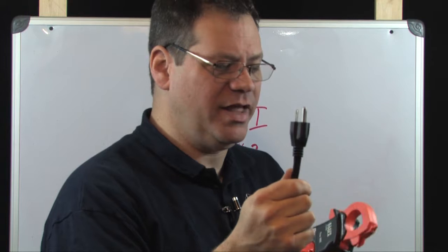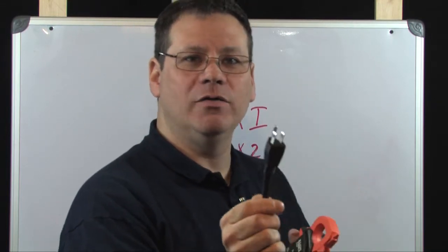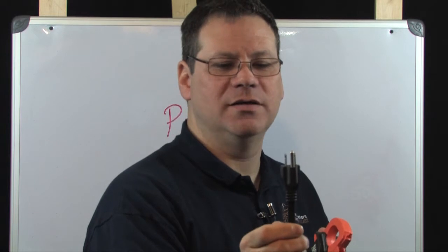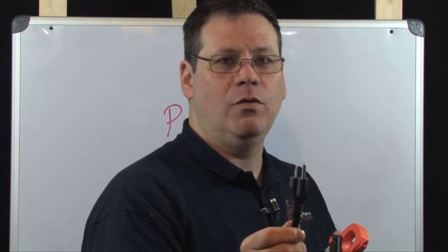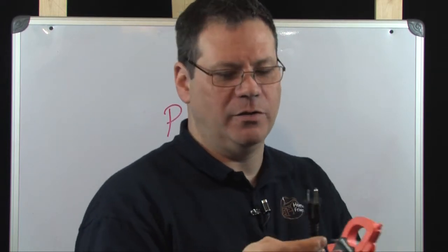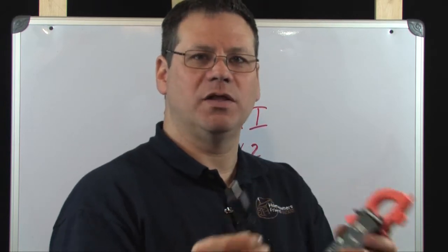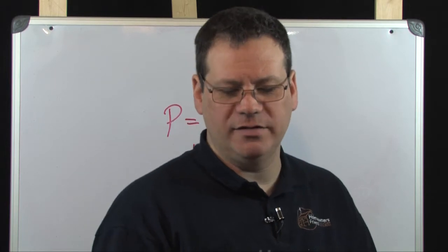So you can't just clamp over that with this device. It won't work. You have to get only one of the power carrying conductors, either the hot or the neutral in this case. So, short of taking this cable apart or splitting it or something, which you could do, I guess you could take a razor blade and just slice in the groove there and just pull it apart, and it really wouldn't hurt the cord, but it does knock the integrity to some extent.